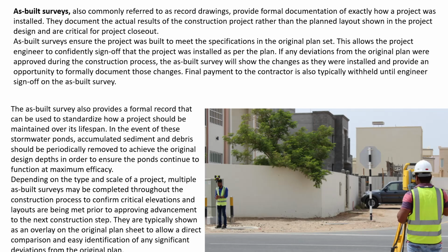In the case of these stormwater ponds, accumulated sediment and debris should be periodically removed to achieve the original design depth in order to ensure the ponds continue to function at maximum efficiency.